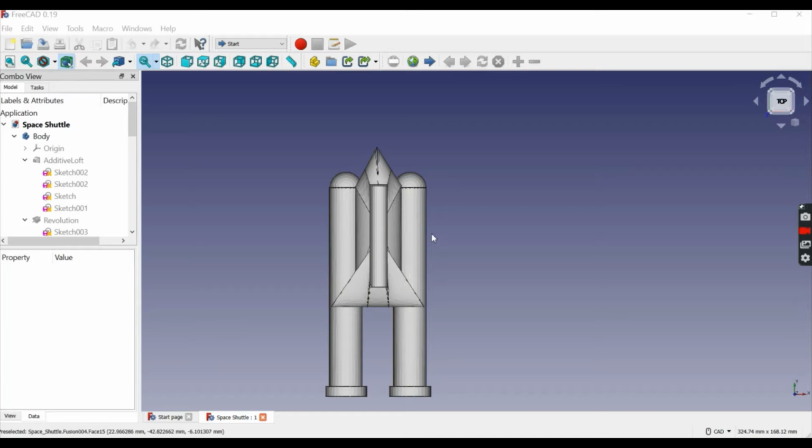it a cylindrical look. I used the part boolean operation, or to be precise, the union operation in the part boolean feature to create the front and the rear ends of this propellant. I merged first the hemisphere with this cylinder for the front end, and for the rear end I did it with two cylinders. Then I mirrored this right one to create the left one.